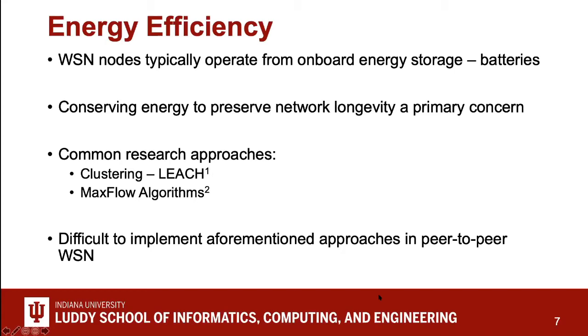So common research approaches for maintaining energy efficiency, one big area is what is considered clustering. And this is essentially where nodes that are of similar distance or similar battery reserves will cluster together and share information within a tight group. If they're physically closer, ideally they're able to send data with less RF power, which requires less energy.